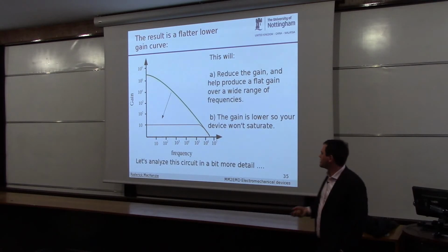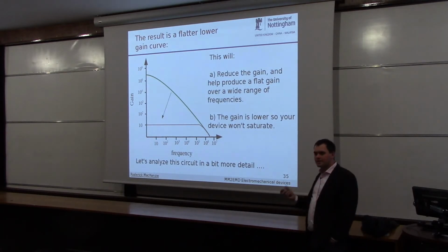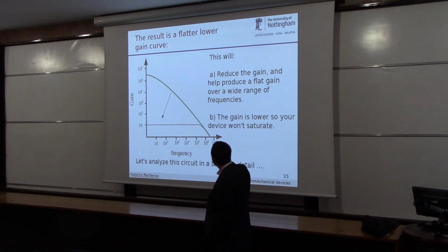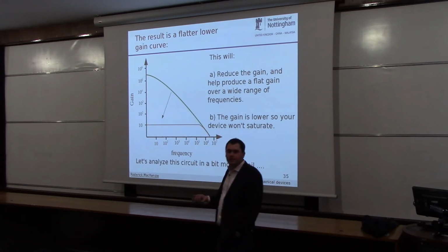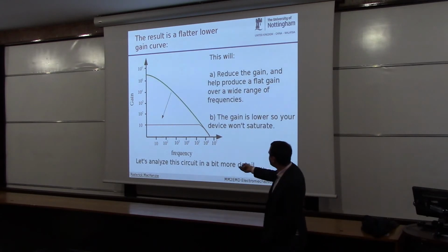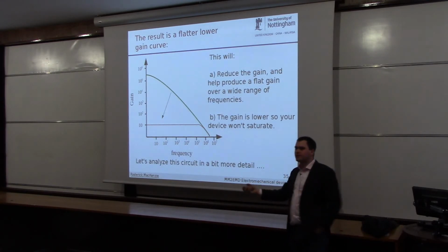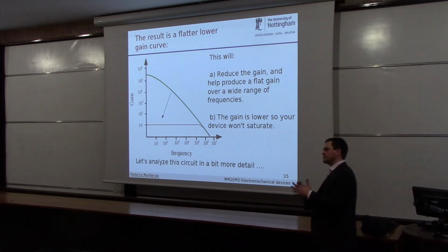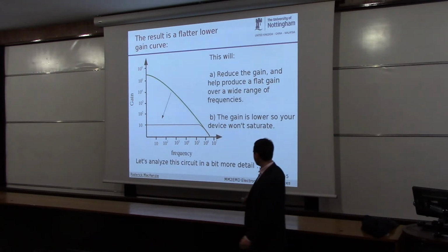So this turns this component into a useful circuit that you can use in your electronic devices. We now have a useful gain, and notice it's flat from about 0 hertz all the way up to about 1,000,000 hertz. So this is also a uniform profile. Now we no longer have our female voices being amplified less than our male voices in our telephone system.